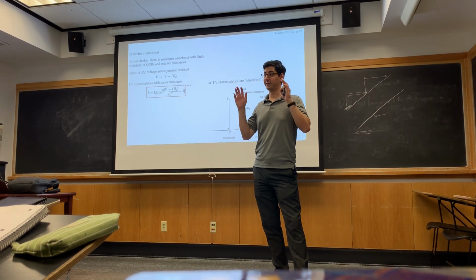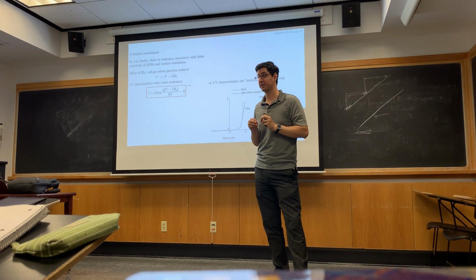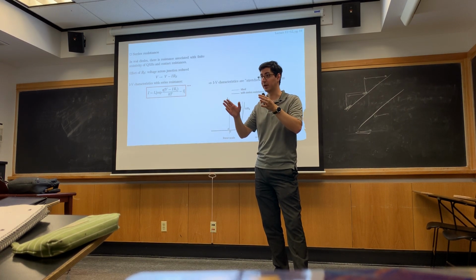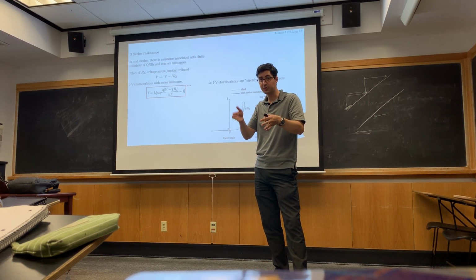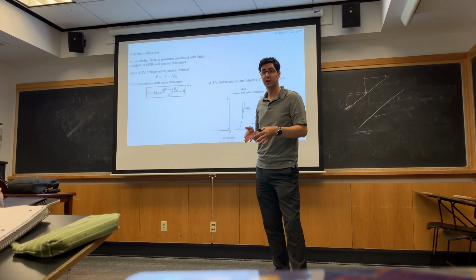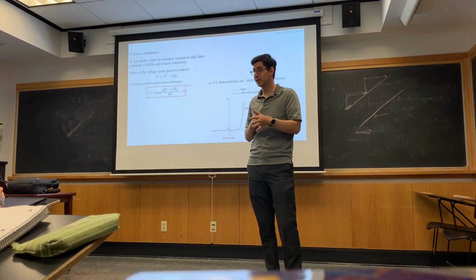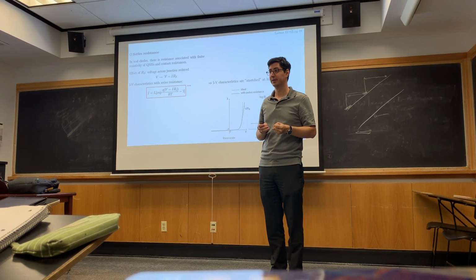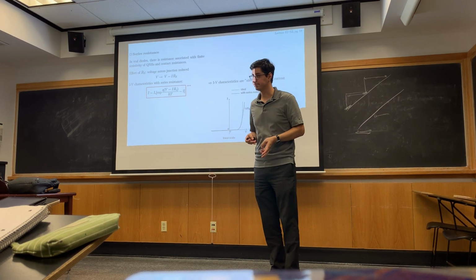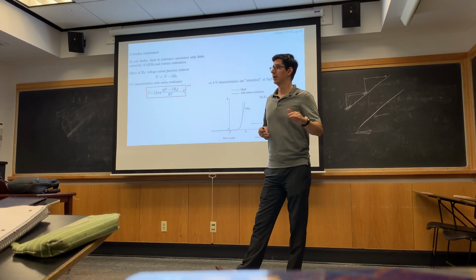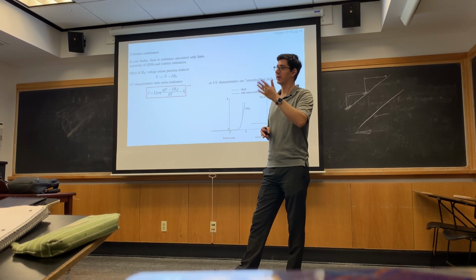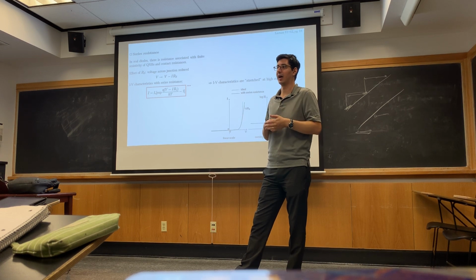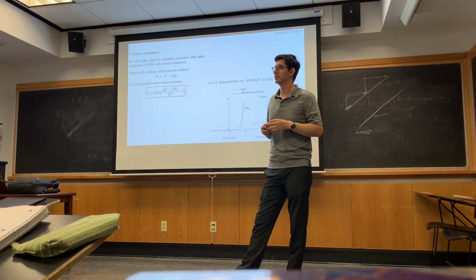And keep in mind, the effective resistance of your junction is changing as a function of voltage. You got your junction, that's what we've been studying so far in a p-n junction. Its resistance is dynamic. How do we know that? If we plot I versus V, where V is the junction voltage, is that linear? No, it's this exponential of qV over kT minus 1. And so the effective resistance, if I just calculate the resistance as V over I, is changing as a function of voltage.